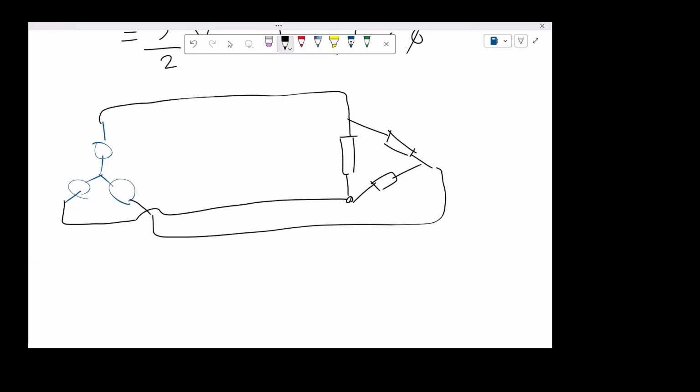The good thing about single phase is that you want to deal with one phase. But here, if you want to deal only with phase A, and this is delta connected, you have to go through at least 1 more phase and then come back, right? So you have to consider both phases. That really ruins everything that was good about a single phase equivalent.